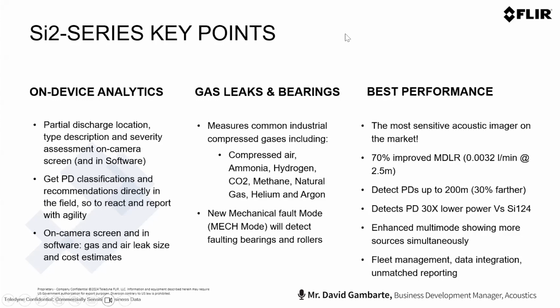It's an extremely sensitive acoustic imager. We have a lot of proof of it. We are very happy with the performance of the solution. It's able to find really small phenomena, for example in PDs, which is not so common in acoustics. The minimum detection leak rate is 0.0032 liters per minute at 2.5 meters, which is a very, very small threshold.